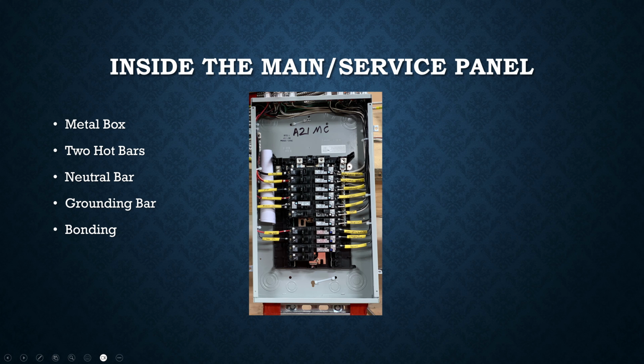So that's the basic premise of this whole electricity thing, right? You're trying to create loops, trying to create circuits, and you do that by connecting one piece of metal to another piece of metal. So when you bring in, let's say, one hot big wire and you screw it down with this lug, it's connected to a big bar strip, and that strip is running down here.